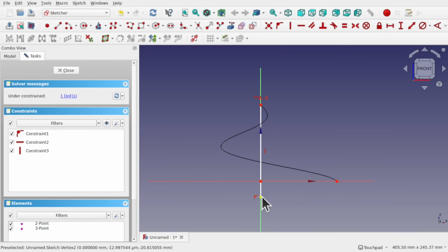To do that, I'm going to add some construction geometry between here, which shows the edge. Use a line, come in and constrain coincident to this point and then coincident to the point we've imported from the helix. Make sure it's coincident to the point and not a point on object constraint along the horizontal axis. Right click or escape to get your mouse pointer back.